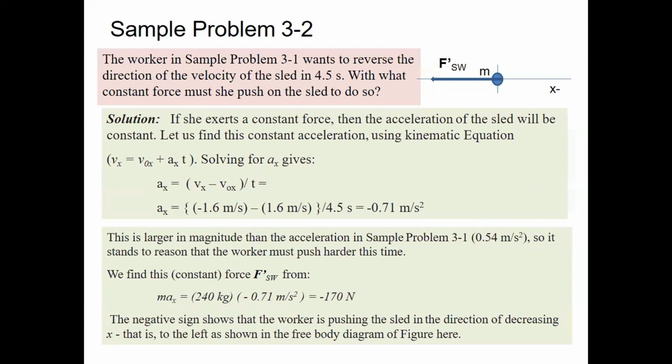Here the problem gave us the final velocity, the initial velocity and the time, and we had to figure out the acceleration, and from acceleration we came to know the force. So there are two ways of approaching a problem in dynamics. One is that we are given the force, or the net forces or the resultant forces, from where we find the resultant force. From the resultant force, we go further to find the acceleration, and from acceleration, we find velocities, displacements, position and the time.